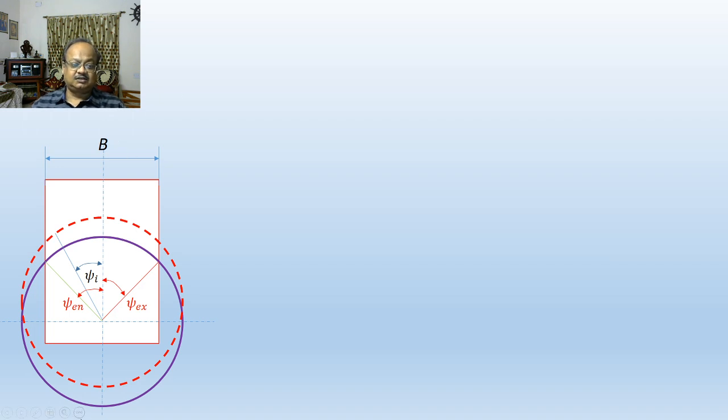This is the width of the job. This is the diameter of the cutter. Last time when we discussed, we assumed that the width of the job is equal to the diameter of the cutter. This is much more actual industrial application where the width of the job is less than the diameter of the cutter, for which you have an entry engagement angle and an exit engagement angle, which are not minus pi by 2 and plus pi by 2. They are something less than 90 degrees on both the sides, and this is the instantaneous position of the insert. This is the instantaneous engagement angle.